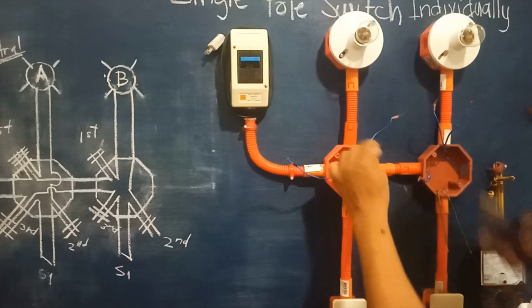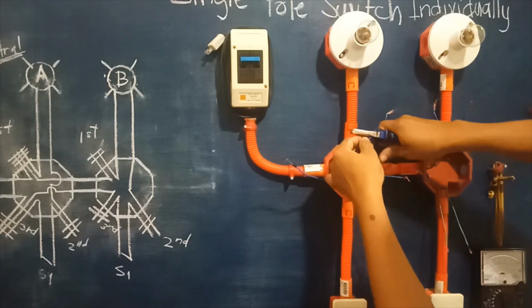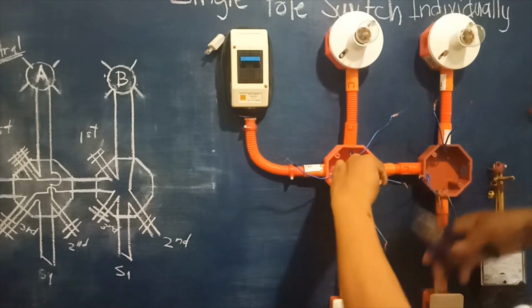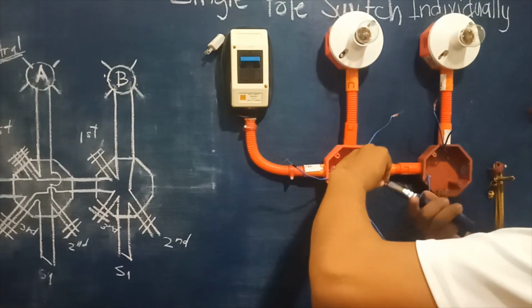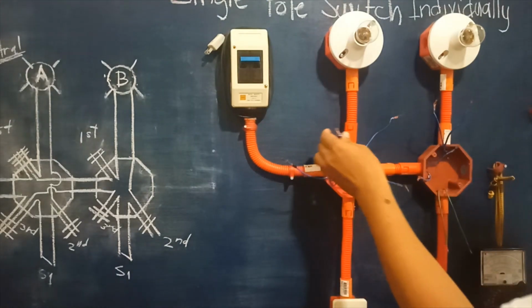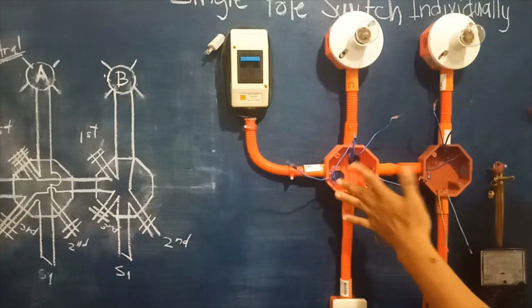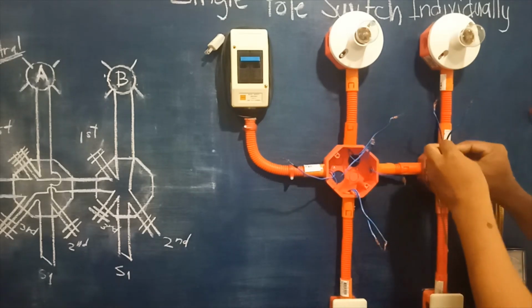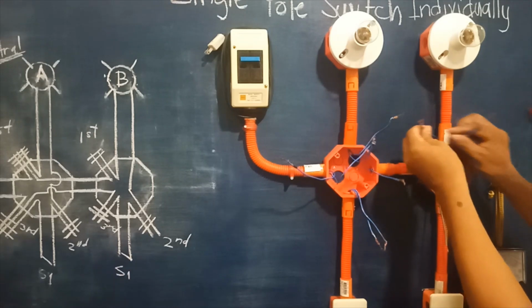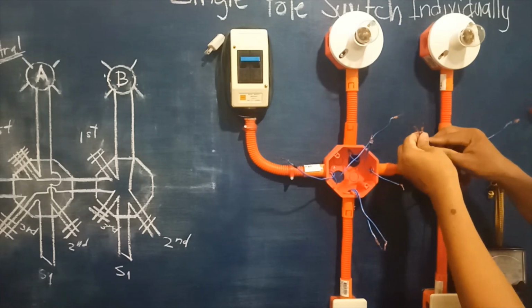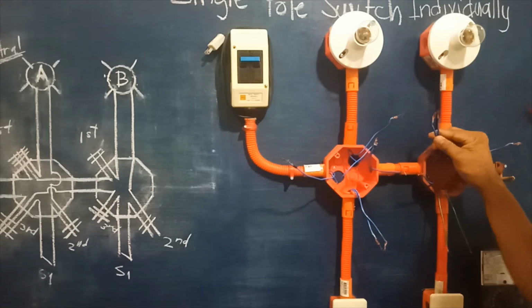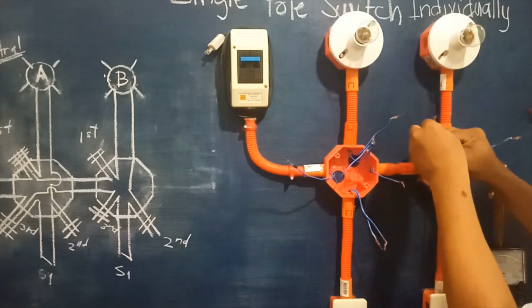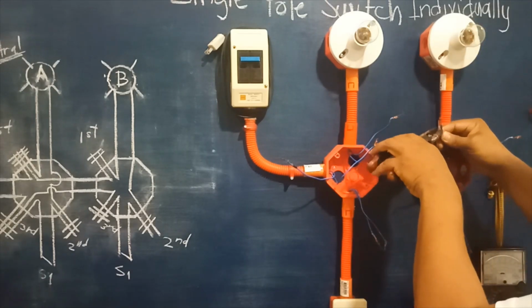Okay, then remove some other parts in the last part. Okay, that is the first cycle in this first junction box. So meaning to say, this wire here, this one, is also connected to our neutral connections from our bulb B. Okay, so this one.